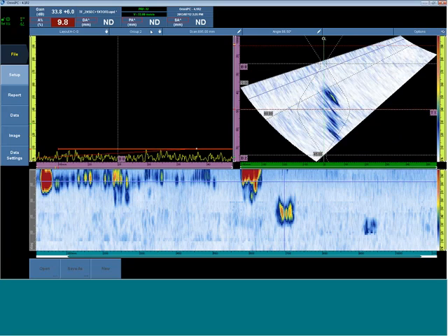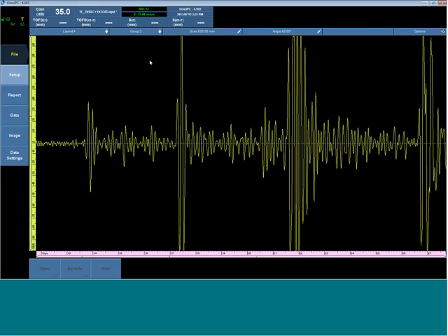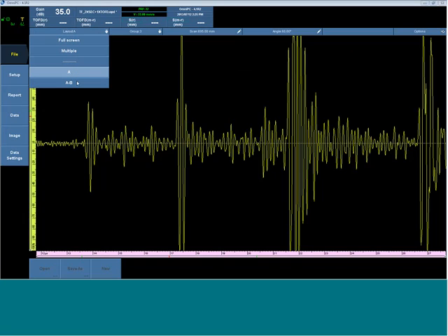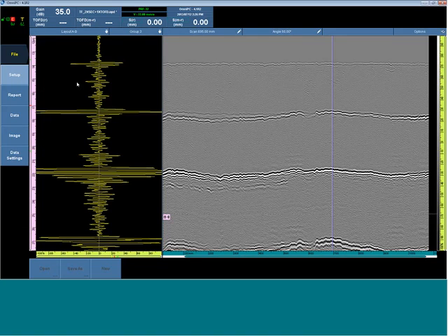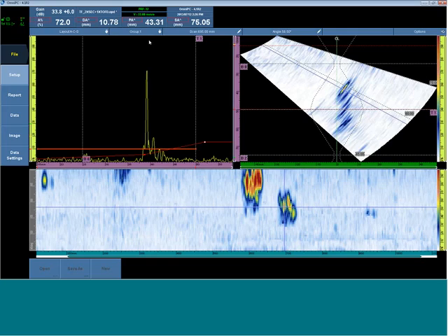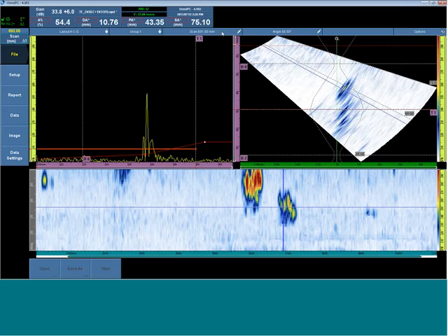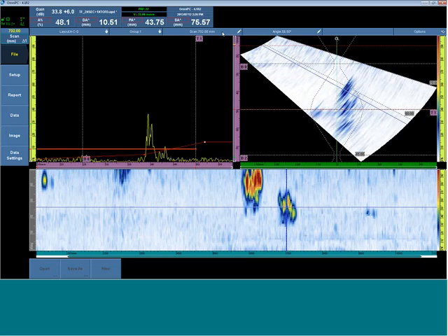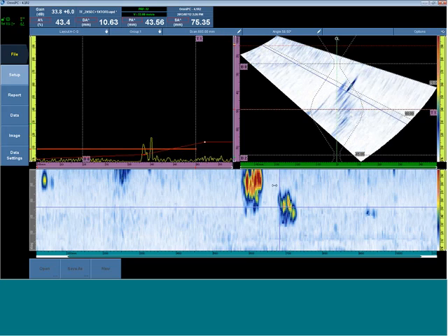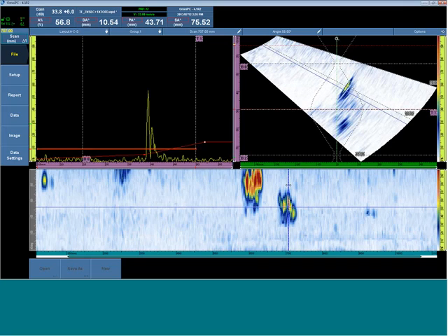It can then be manipulated directly on the title bar or by manipulating it on the S-scan or C-scan. Options include a grid for the A-scan that's customizable, the weld overlay, the legs for the ID and OD. This would allow me to turn on or off any cursors and gates. The gates are for display only.